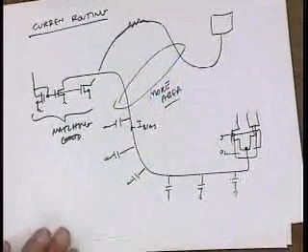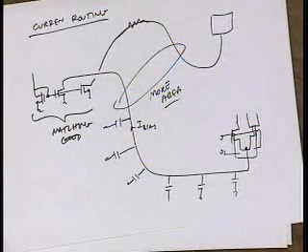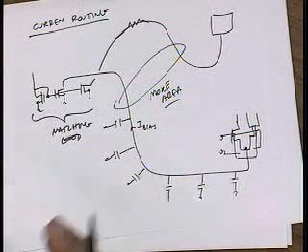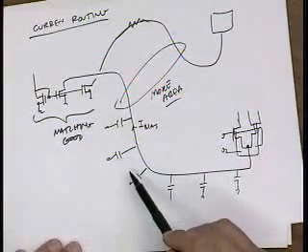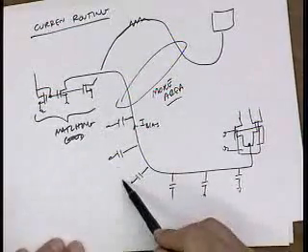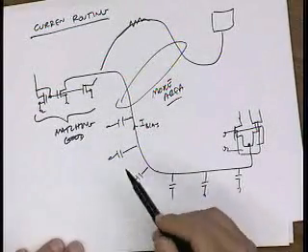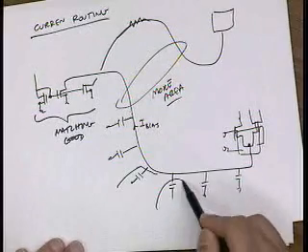Why is it that I don't like capacitance on this line? Yes, Debo. Coupling between. Yeah, sure. That's an issue. But I mean, you'll get displacement currents, right, that are AC, that'll put in noise. Yeah, you're absolutely right. So both you and Debo were talking about substrate noise that could get into your bias.